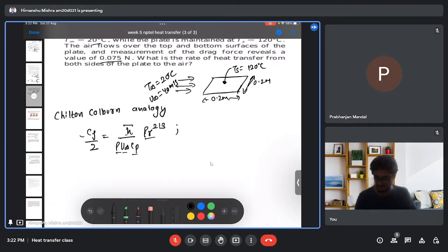I can first find CF. So to find out the heat transfer, we need a heat transfer coefficient h bar. So we need to find this h bar. To find this h bar, we need CF, Pr, and Cp. Cp we can find from any book or internet. It is just a property of the fluid, and here we need to find the drag coefficient and the Prandtl number. So to find the drag coefficient, I can write as...